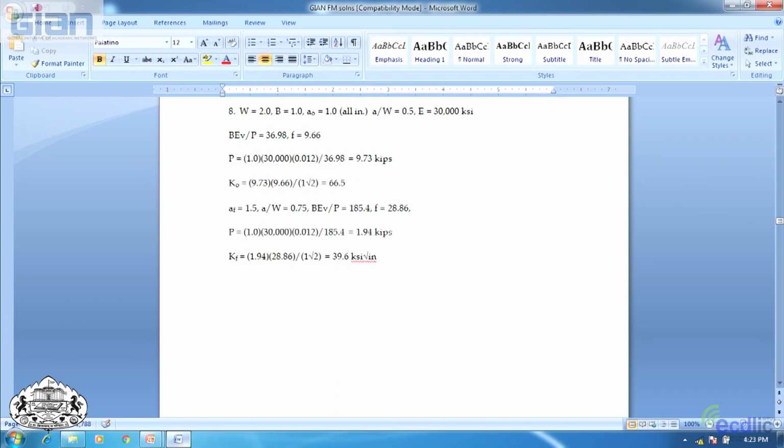Notice the load drops considerably. The K drops by almost a factor of 2, not quite. So if you were doing the bolt load test, you would assume then that that is the K1 SCC. If you weren't sure about that, you could do several tests, some shorter, some longer, some duplicates, but that's that one.